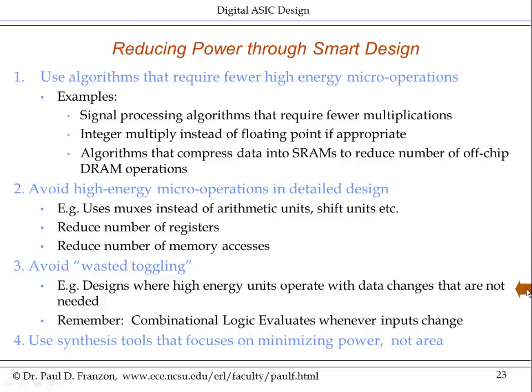Thirdly, don't be wasteful. If you have a logic unit that through some aspect of the design is toggling and you're not using the result, then that is wasted power. And this scenario is actually quite easy to do accidentally, and I'll show you some examples in a moment. So you as a designer might even have to add features to prevent wasted toggling and wasted power consumption. Remember, your goal here is that each logic toggle in your design is contributing directly to the end computation that's required.